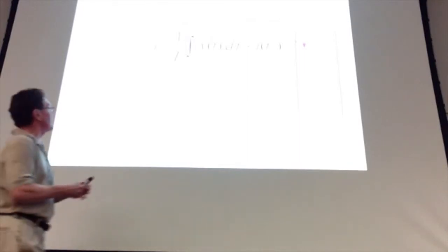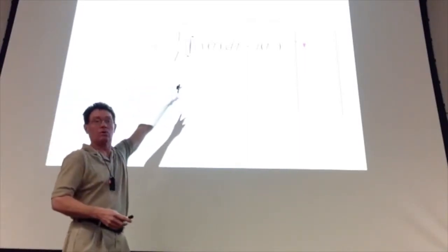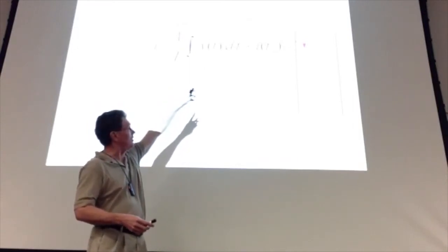All right, so again, once we solve for the current, we have 1 over L, the integral from some initial time point to some final time t of the voltage across the inductor, plus the initial current. So it's very similar to what we had for capacitance. For capacitance, we had V of t is equal to 1 over C, the integral of the capacitor current, plus an initial voltage. So it's very similar. All right, and this is what we're going to exercise today. And then the power is just 1/2 the inductance times the square of the current through it. Okay? And I showed you some videos.